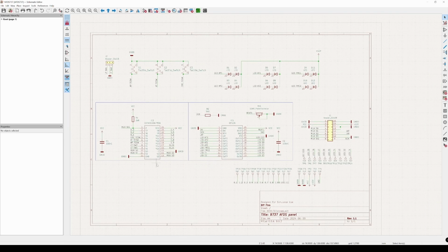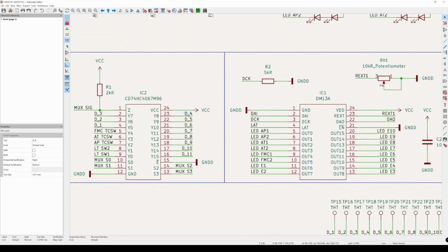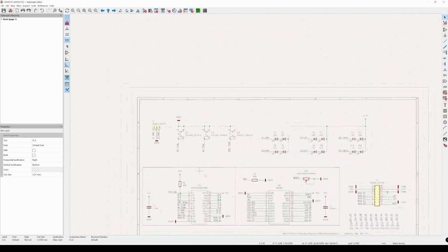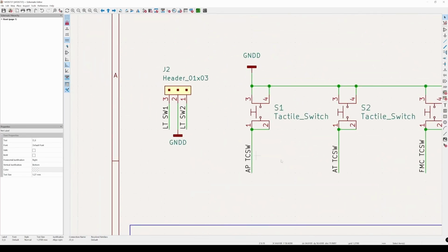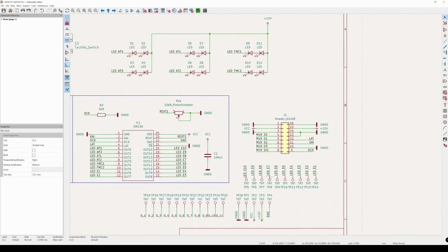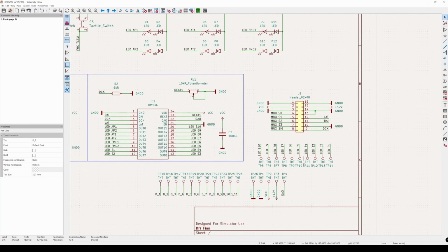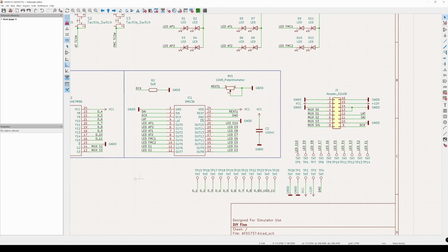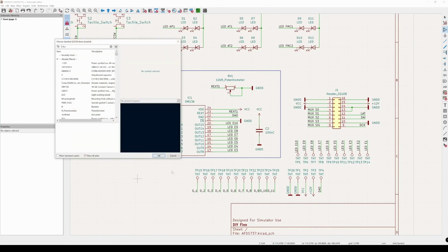Alright, welcome back. Now I have added the LED controller as well, wired up everything. I've added the sort of redundant output pins here, and we have connectors, and we have some through hole mounting points for all sorts of things that I wanted to add, and these all depend on your specific design, and these would be added exactly the same way as any component.